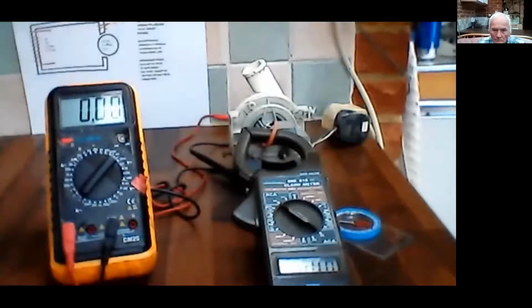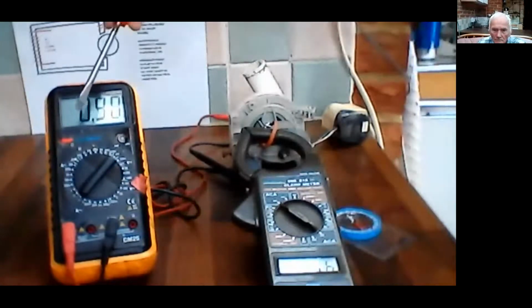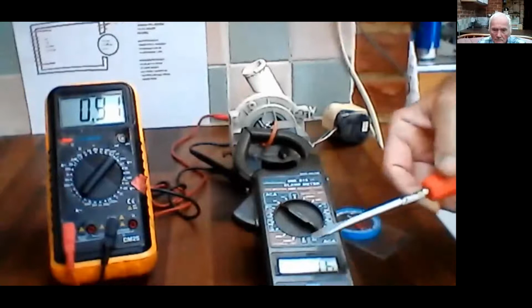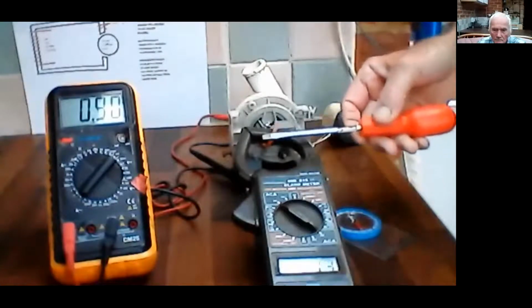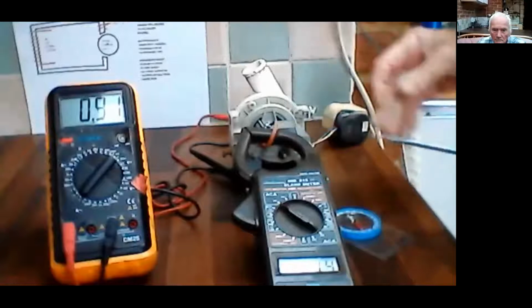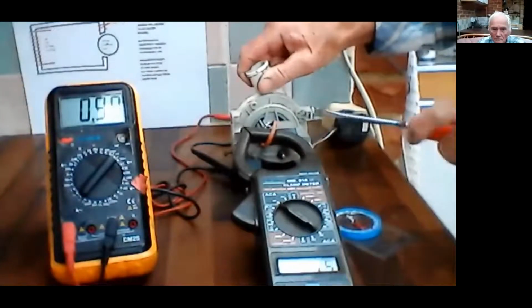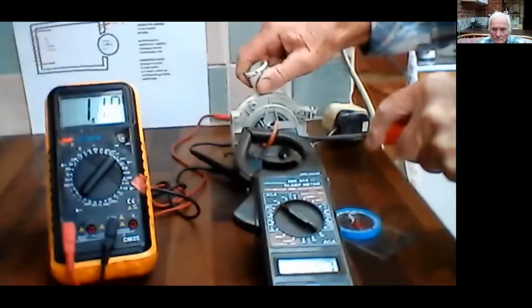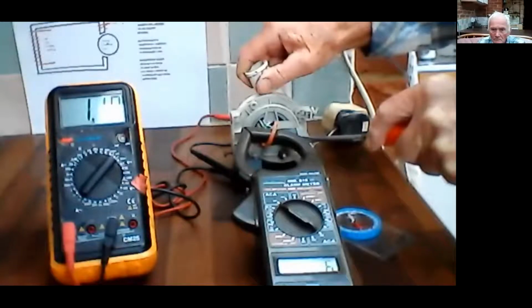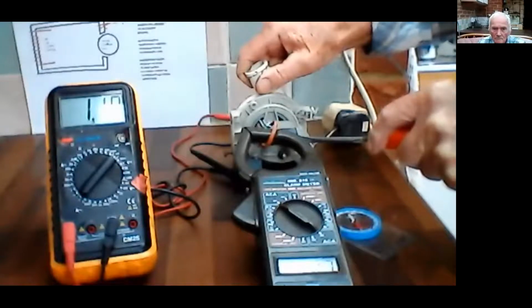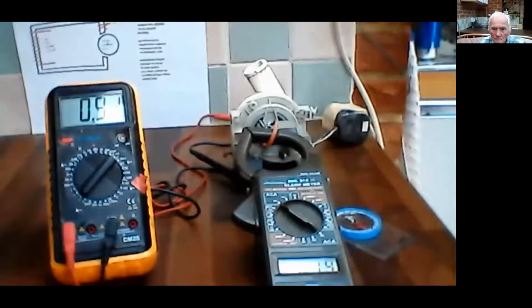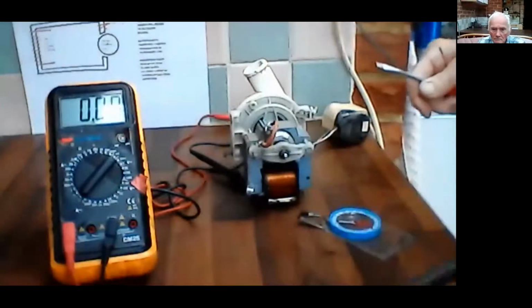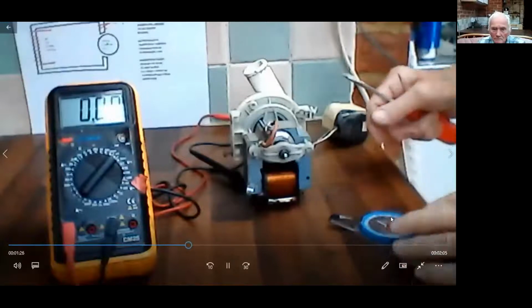So we switch on the motor, and immediately get about 0.9 amps on the primary winding and 11.5 on the secondary, or the teaser winding here that's making it soft. If we now jam the motor, then up goes the secondary to about 12 and about 1.1 on the primary winding. But let me now unplug it again. And if we take it away now, the magnetism's gone out of here.